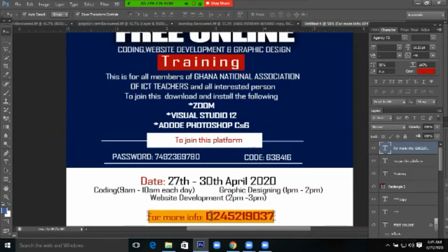You can see from the end that the F has overlapped the rectangle box. So you hold down the side of the text, hold down the Alt key and the Shift key, then you decrease it into this rectangle box. Now I'm done with the work.